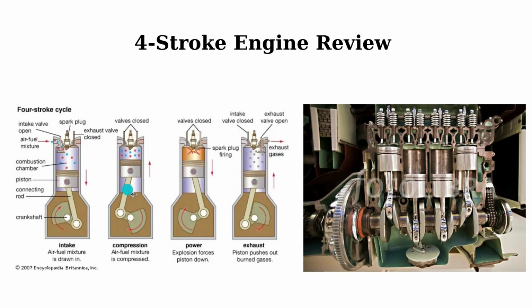During the compression stroke, the piston moves upward and both valves are closed. This compresses the mixture, increasing its pressure and making it ready for combustion. And during the power stroke, the spark plug ignites the compressed mixture.